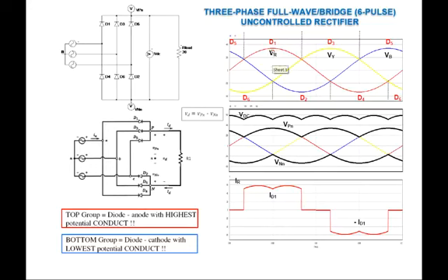We're going to look at the commutation of diodes from D1 to D2, D3, D4, D5, D6. So this is how the diodes switch from one diode to another diode. It is labeled so that in that waveform we have a correct sequence of diode operation where I go D1, switch to D2, then D3, D4, D5, D6. Right. So that is why we have the labeling of the diodes, so it's D1, D3, D5, D2.